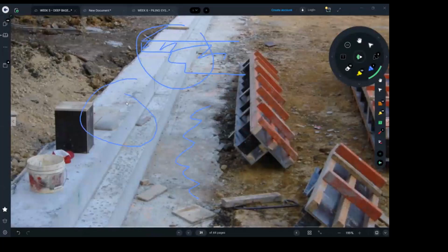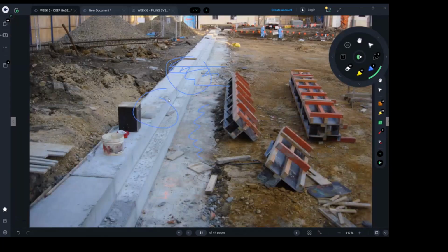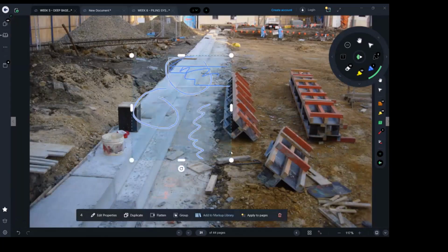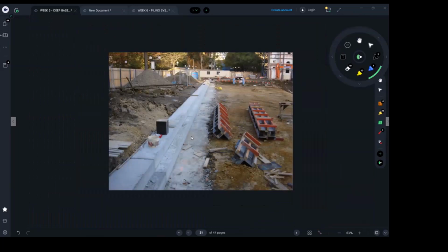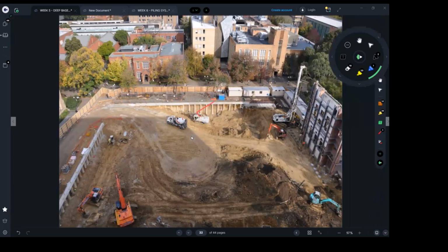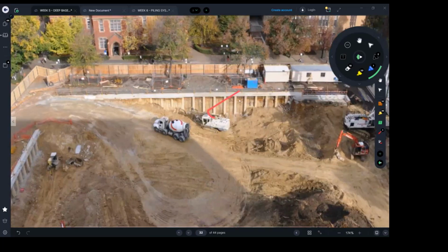That's where you got all the steel bars connected together between the pile cap and the piles. So again, remember the steps. Excavate a hole. If it was the CFA method, which is definitely used for large projects and deep basements, excavate the hole. While you excavate with the CFA, you pour the concrete, submerge the steel with a decent lap, and put your pile cap. Then next, we will start getting the trucks to excavate.